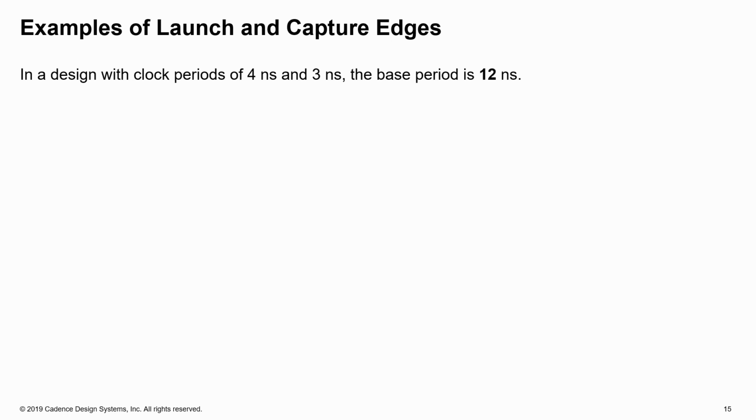We are asking for a falling to rising, so we look for the worst case falling edges, and then look for the most restrictive capture.